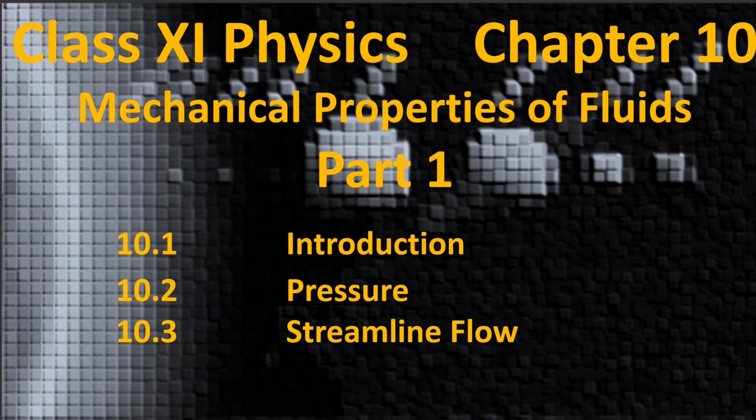Shear stress can change the shape of a solid, keeping its volume fixed. The key property of fluid is that they offer very little resistance to shear stress. Their shape changes by application of very small shear stress. The shearing stress of fluid is about a million times smaller than that of solids.